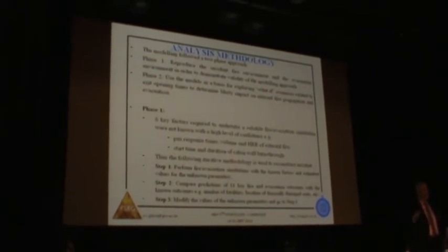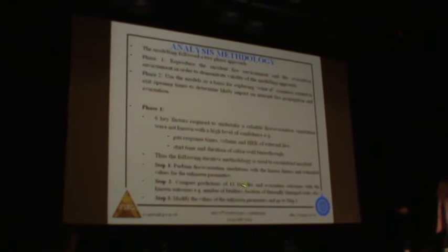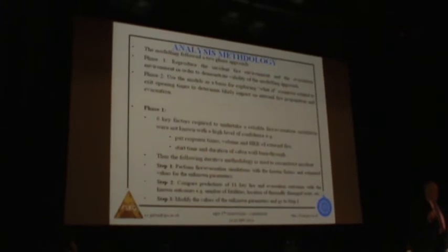And so what we did was an iterative process in the fire and evacuation modelling where we would make the best educated guesses for the unknown parameters, run the simulations and see how well it matched what actually happened. When we saw there was a bit of a mismatch, we would change some of the values and go through the process again until we got good agreement. We had 11 key fire and evacuation outcomes we could test the model results against. And we went through this iterative loop, surprisingly, very few times. We had to go through this loop 3 times, and then we finally got a very good agreement with the actual fire and evacuation.